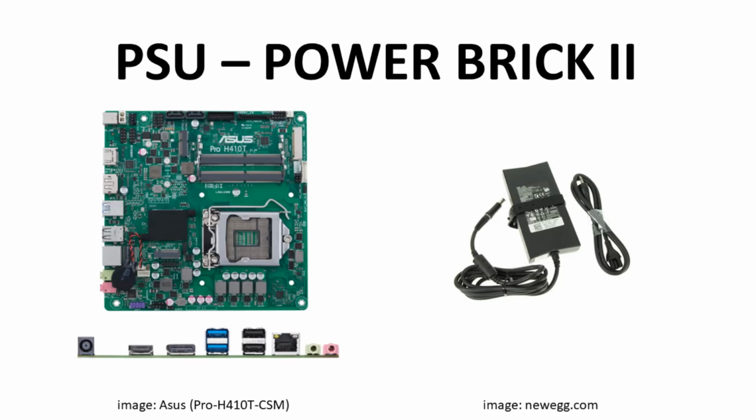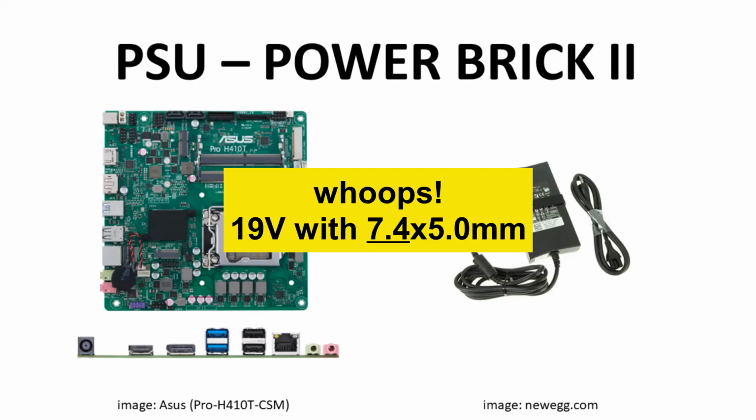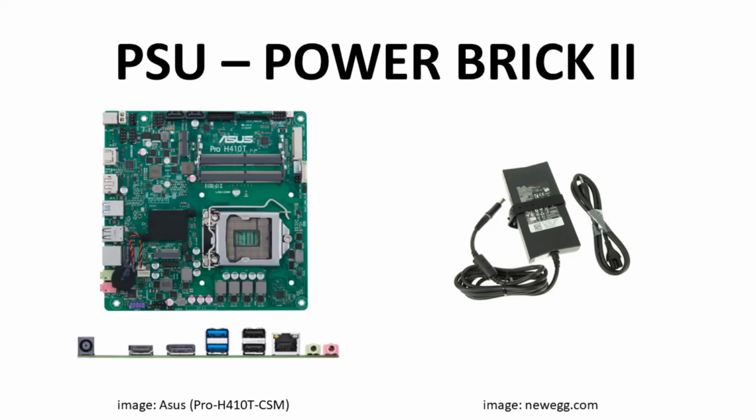Many are 19 volt with a 9.4 by 5 millimeter plug. Some are 12 volt with a 5.5 by 2.5 millimeter plug. A few are less picky about the exact voltage and accept anything from 12 to even 24 volt input. But the jack still needs to be the correct size. You'll need to read the manual for specifics.